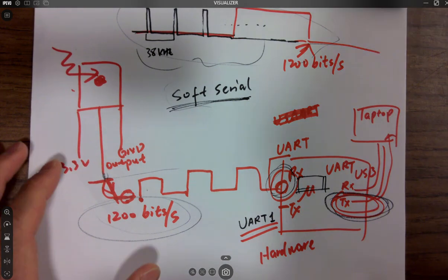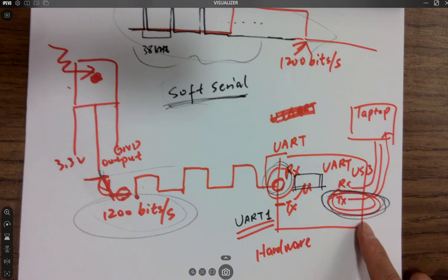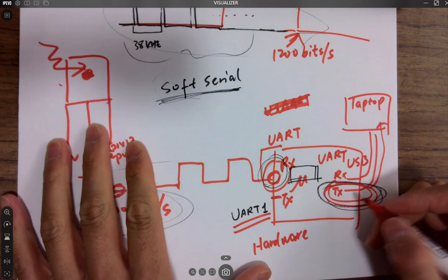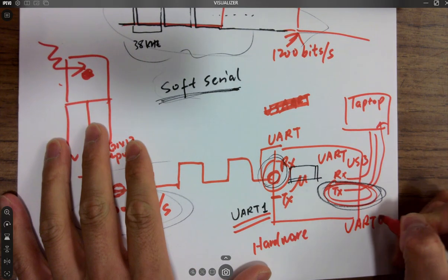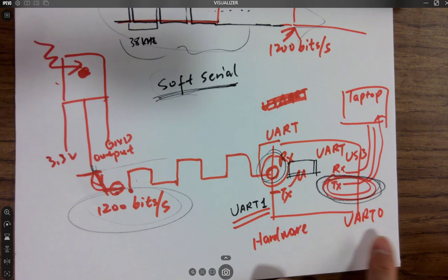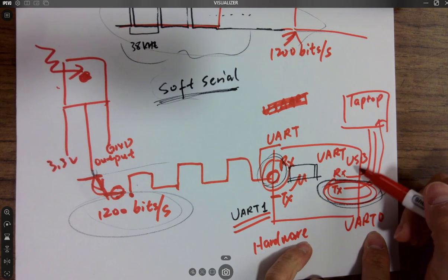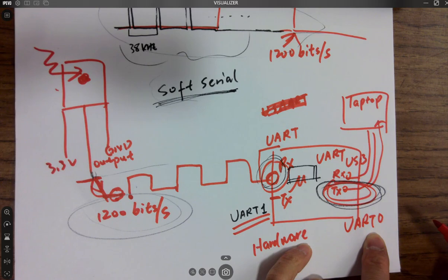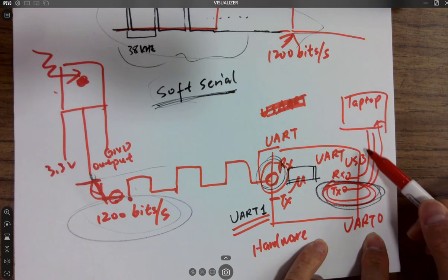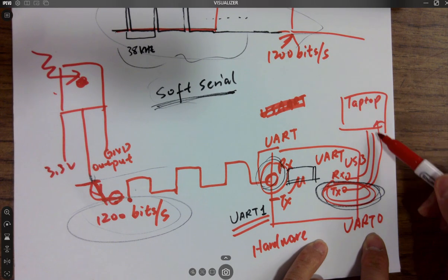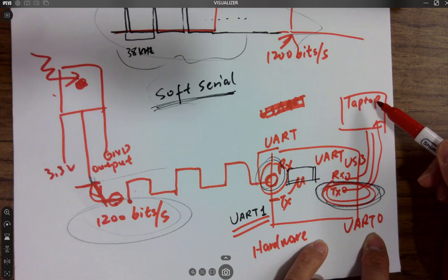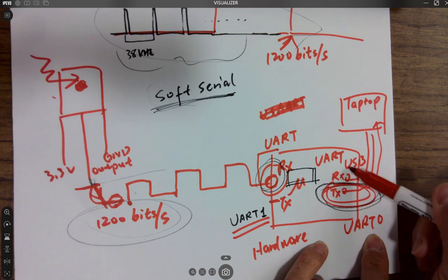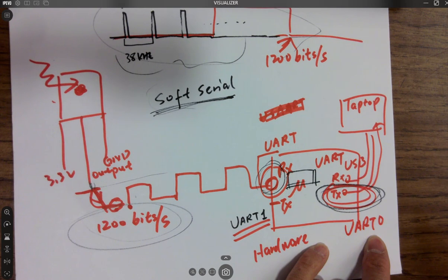So in your setup function, you need UART0 because this is already on the board. You cannot change it. That's the UART0 RX0 TX0 module. It's already physically shorted to the USB and eventually goes to the laptop, right? So that is why I cannot use UART0 anymore. I have to find out another UART module.